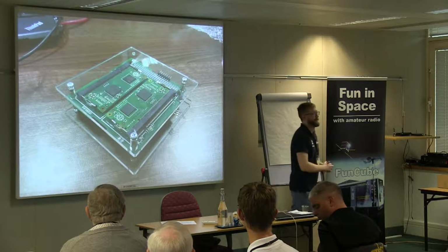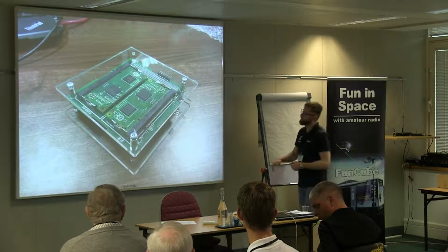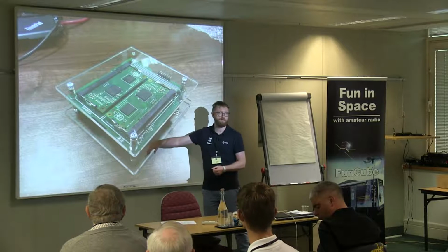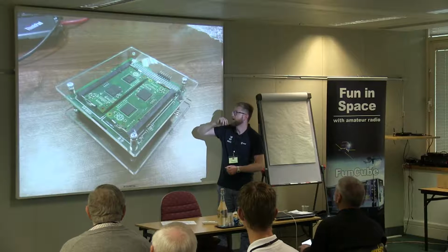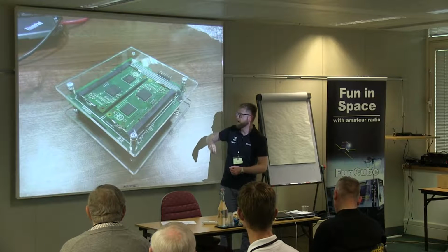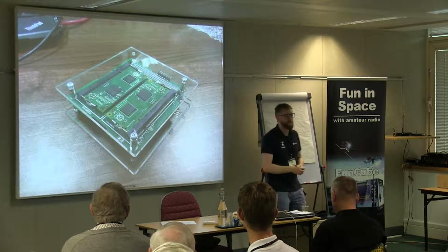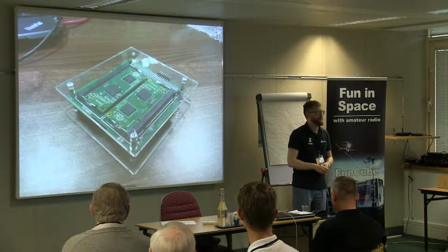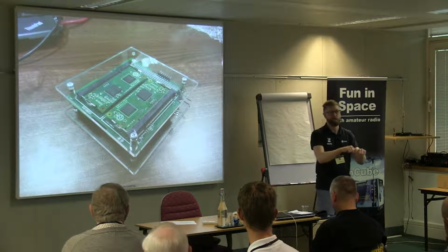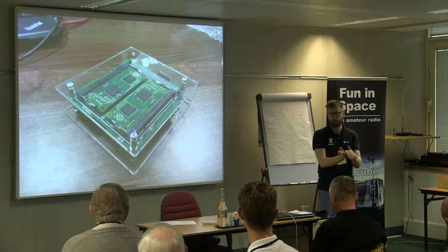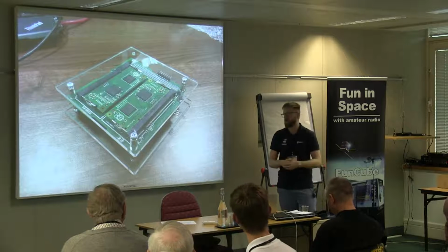In 2015, that's only 10 years out, I showed you the sort of version 1 of what our onboard computer was going to look like for this. And this was built by a student called Oliver. Essentially we designed a dual redundant Raspberry Pi compute system. And these Raspberry Pis could then operate either as hot redundancy, where they're both on and both actively doing the same thing, so that if one goes wrong, you can switch, or you can operate them in cold. It gives you a lot of options.